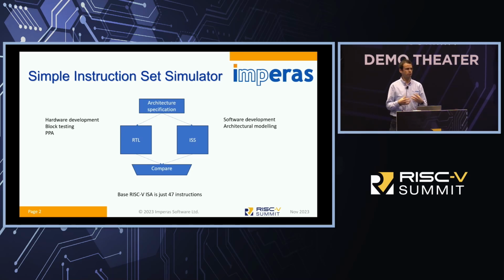So if we think about what it means to develop an instruction set simulator, why you might be doing it, typically you'll start from an architecture specification such as the RISC-V ISA. If you're building a chip on the hardware side, you do your RTL development, block testing, you worry about things like PPA. And on the software side, you want your ISS to allow you to do software development, maybe some architectural modeling. And you might use them for verification, where you compare them against each other, check for quality of results. And for the base RISC-V ISA, you've just got 47 instructions.